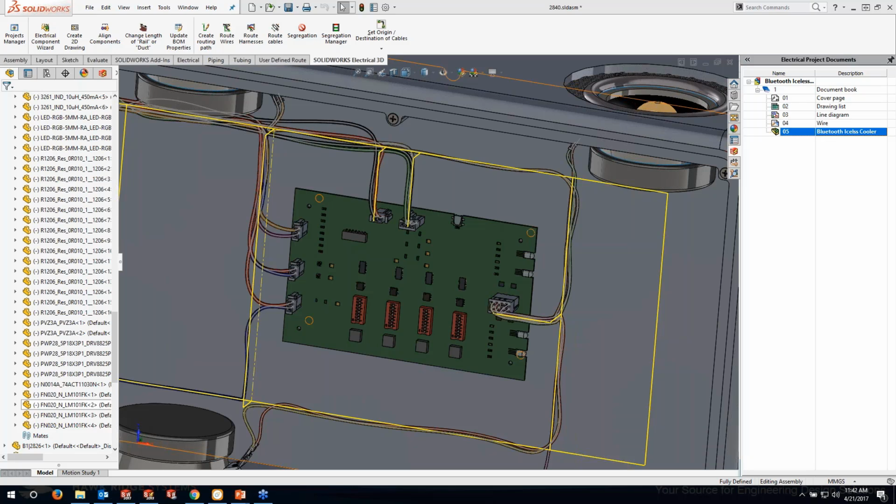So there's a question about how should wires that need to be bundled together be represented? Can I use cable without a predefined cable type? That is a little bit different. You could, in theory, do that, just create a generic cable type. The unfortunate thing about that is that in your report, it will show up as a specific cable, and it would show up on the cable report as that manufacturer's part. If you're just bundling or wiring or holding things together, the schematic really doesn't care if those are bundled or not. It's the 3D that is more of the realistic thing.